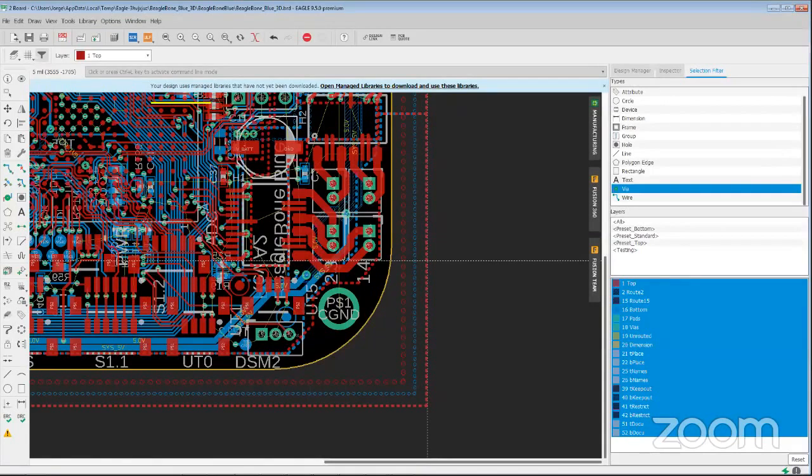We could invert on Gerber. Right, the PS inverted, the PostScript drivers, those require old CAM jobs, so you can't make it on a new version of Eagle. But if you did it before, then you could use that CAM job on the newer versions of Eagle, because the newer versions still can run the old CAM jobs and all the old drivers. So those would be my recommended ways.